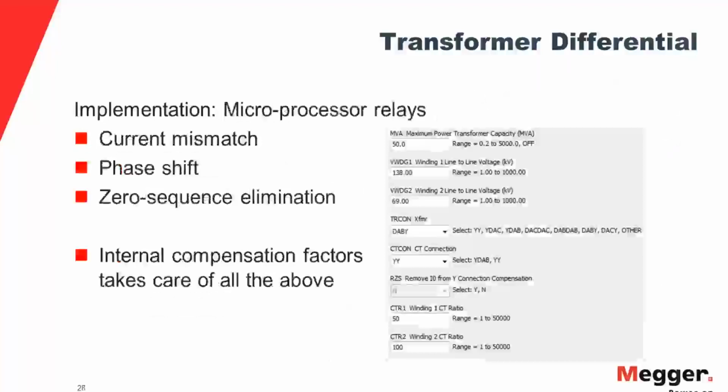So you will also prevent the zero sequence current taking effect into the secondary circuit, because the Y side which takes the neutral current, the CTs are connected in delta. There is no way that the neutral current will flow through the delta connected CTs on the secondary side. Similarly, there is no zero sequence current on the primary side, so you will not see that on the primary CTs as well.